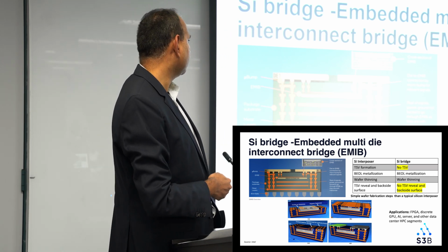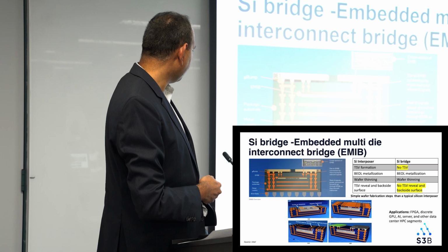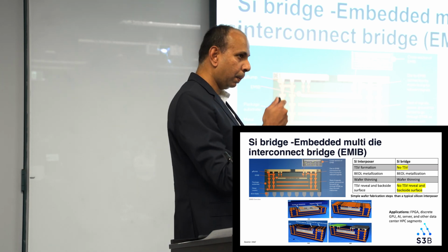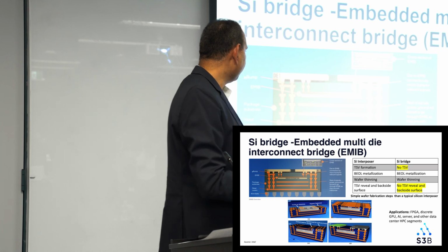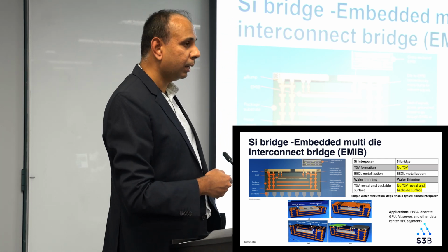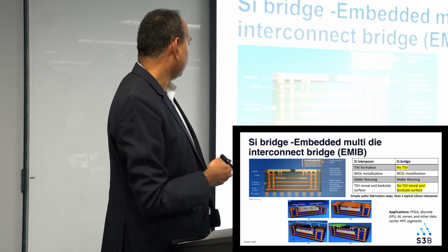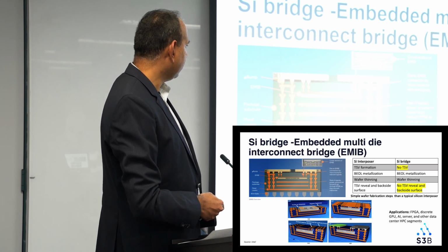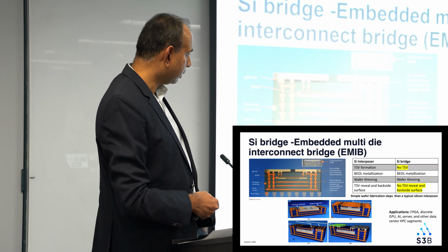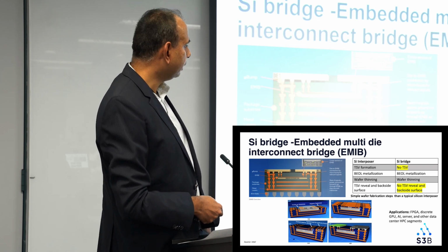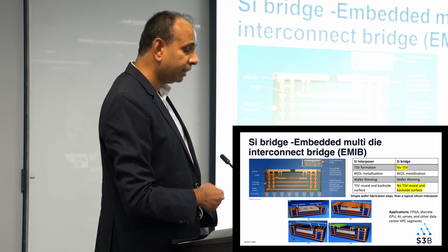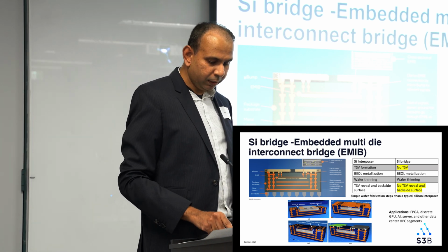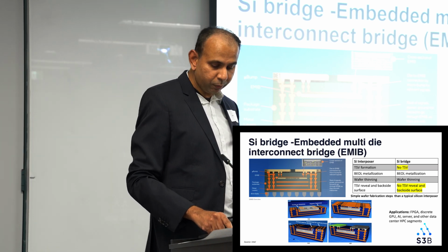There is also no need for any backside surface process. This simplifies the advanced packaging of the 2.5D process, thereby increasing the throughput and reducing the cost. Typically, I think this EMIB process is heavily used by Intel in the AI sector, and even IBM is looking into the silicon bridge process for their latest devices.